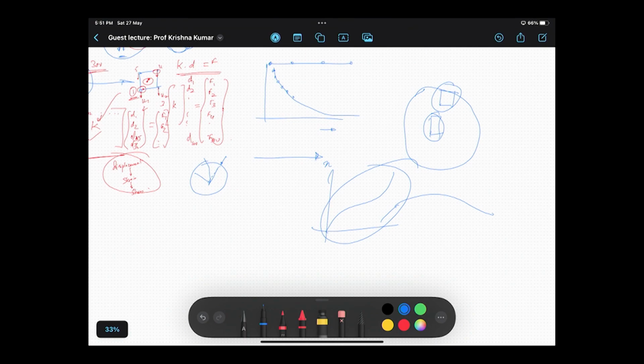Sir, for a small piece of tire, we take a test and we get all the values. But for the human body, like blood and nerves, how do you get those values? Exactly. There have been a number of studies already where they have characterized many parts of the body, almost all parts of it, including cornea. The problem comes when there is a disease state, when the properties change. And that's the future of medicine. How the properties change, and because of that change, how the mechanical behavior varies, is the problem. This is usually done by an inverse problem, by using what is called parameter estimation. You know the result. You already know, if this were the result, what the property is. And then you find out the property.